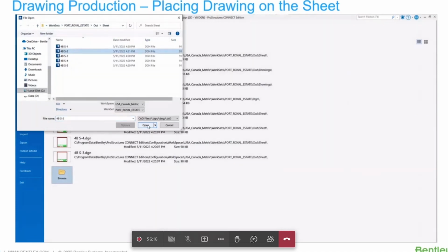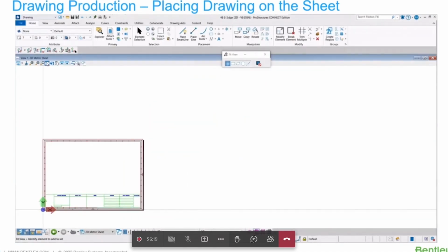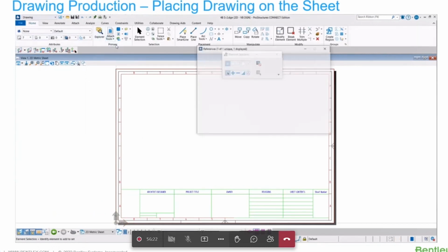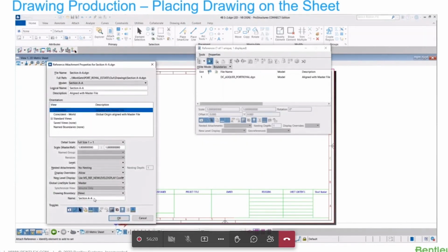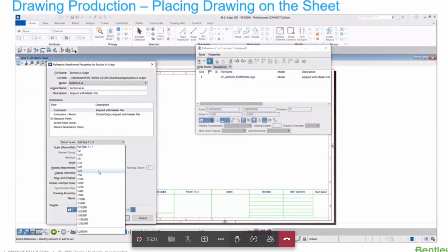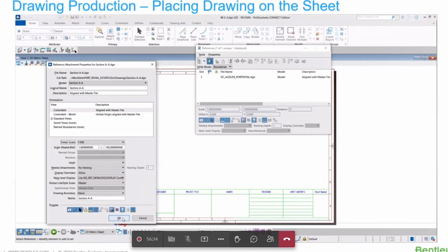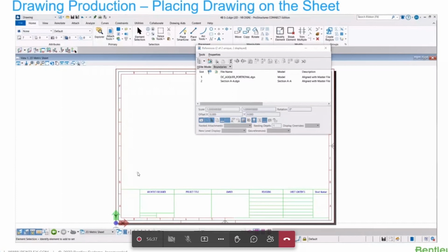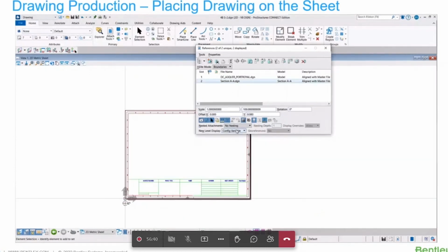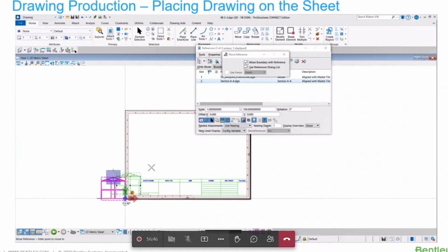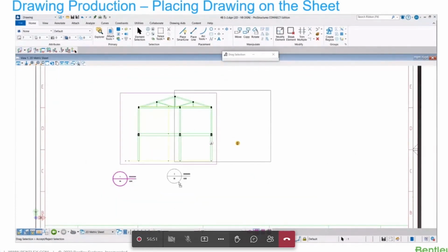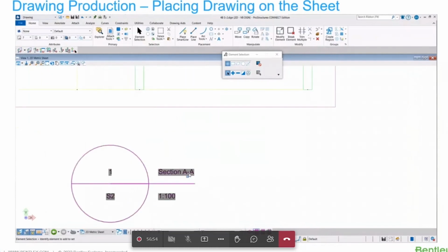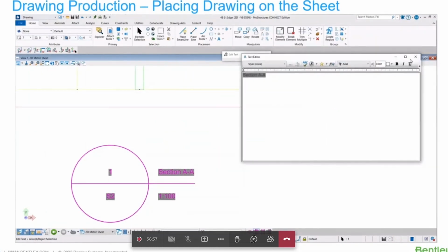This drawing identifier and sheet number will be updated once the sections are placed. So I open another sheet and place this section on this sheet. Okay, I define the scale. It doesn't appear because we need to activate the live nesting, because this is the cut section from our models. Now, if you see, the name is Section 1, the first drawing on sheet S2.